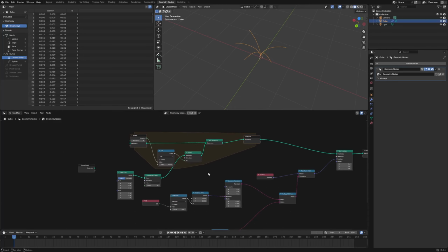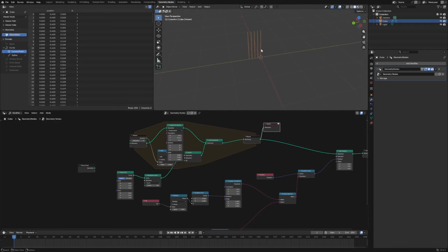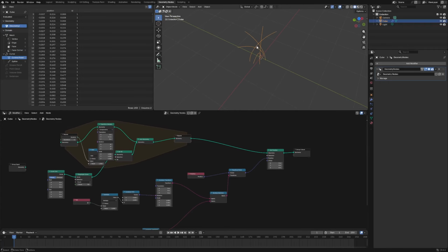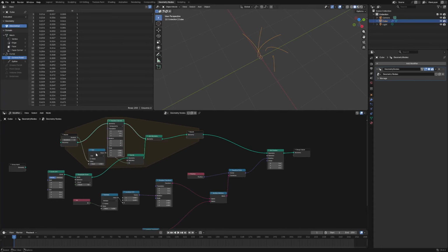It's looking good. What we can also do is add a transform geometry right here. And if we offset this by a little bit, look at this right here. It's offset like this. And then we're going through, getting all of these different changes of the point. So we know we're doing it on the X, so maybe the X is probably going to be best for us. What's cool is this is making a spiral automatically for us.